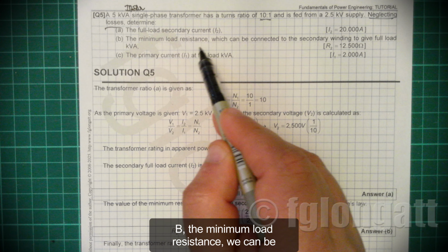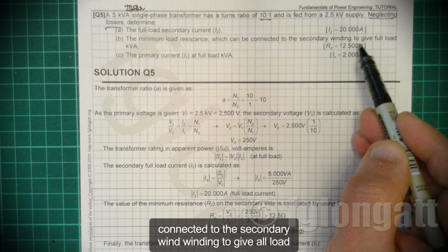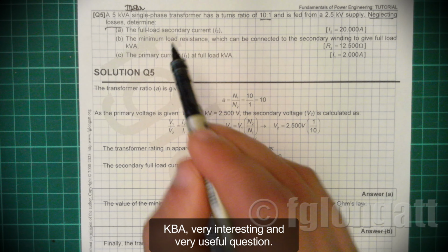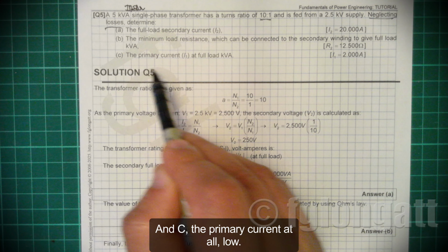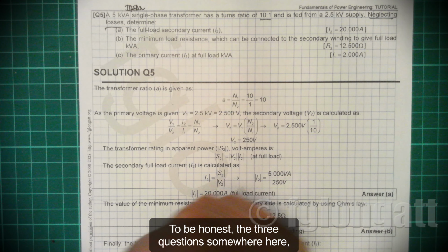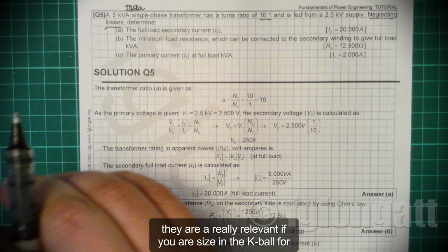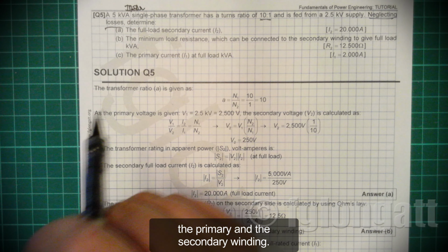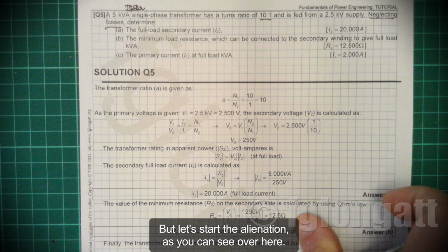B, the minimum load resistance which can be connected to the secondary winding to give full load kVA. Very interesting and very useful question. And C, the primary current at full load. To be honest, the three questions over here are extremely relevant if you are sizing the cables for the primary and the secondary winding of this transformer. But let's start the explanation.